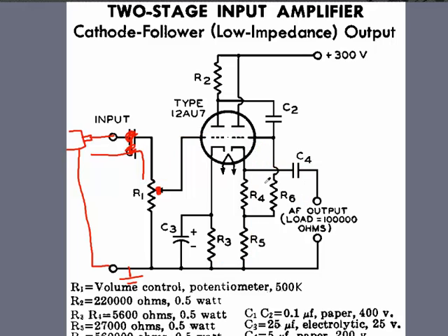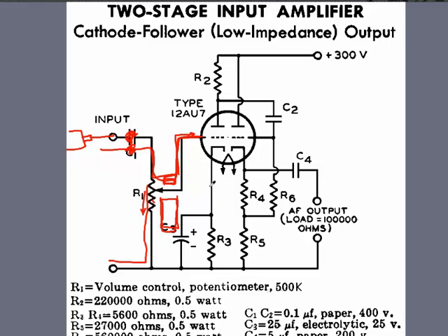But really all you need to know about this is that as current's coming into this node right here, right? If you crank this thing so that there's more resistance here and very little resistance on the top half, the current is more likely to flow into here and go this direction than this direction because you've created a lot of resistance. Remember what resistance was? The opposition to current flow. So as you crank that knob and you put a lot of resistance here, all of a sudden you start flowing more in here. And so you end up with a smaller voltage drop on this side, right? So you end up with more voltage, ultimately more current feeding into this thing, and less of it going straight back to ground, closing the loop on your circuit.